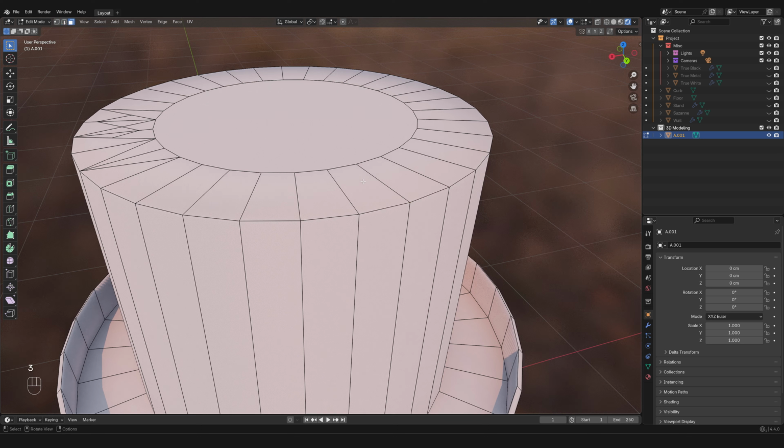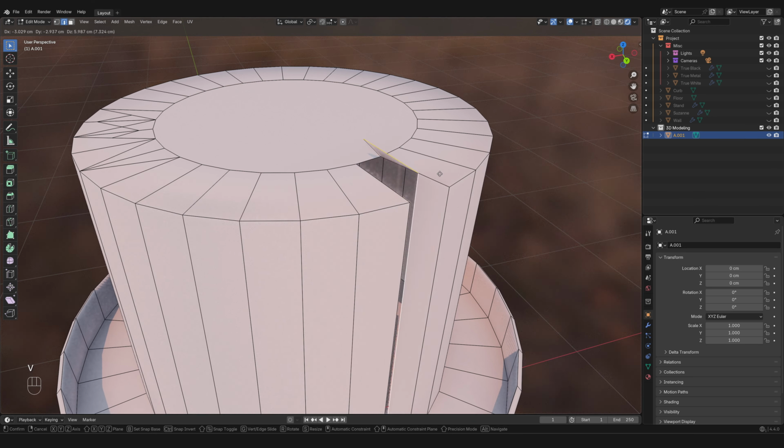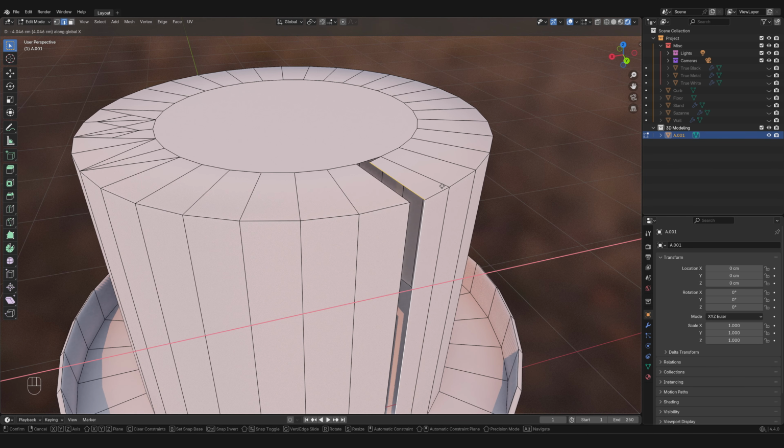And the next thing I'm gonna show you is the rip command, which is V. Now V will sort of detach the edge that you have selected, and it's really cutting through it, basically making an opening for you to make some intervention. And all of these commands that I'm showing you, once you are in this preview mode, just like the move commands, you could press X, and now you have control on which axis you are moving.